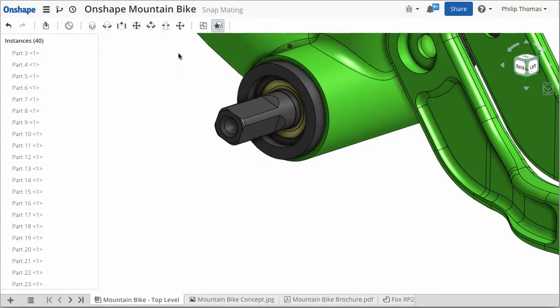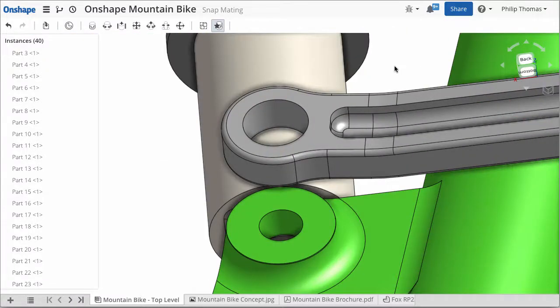For this next example, mating one end of the crosslink connector to the frame, we will introduce the Shift key shortcut. Its function is exactly the same as its use in standard mating, specifically the freezing of the current state of the displayed mate connection points. Let's see how we would use this.